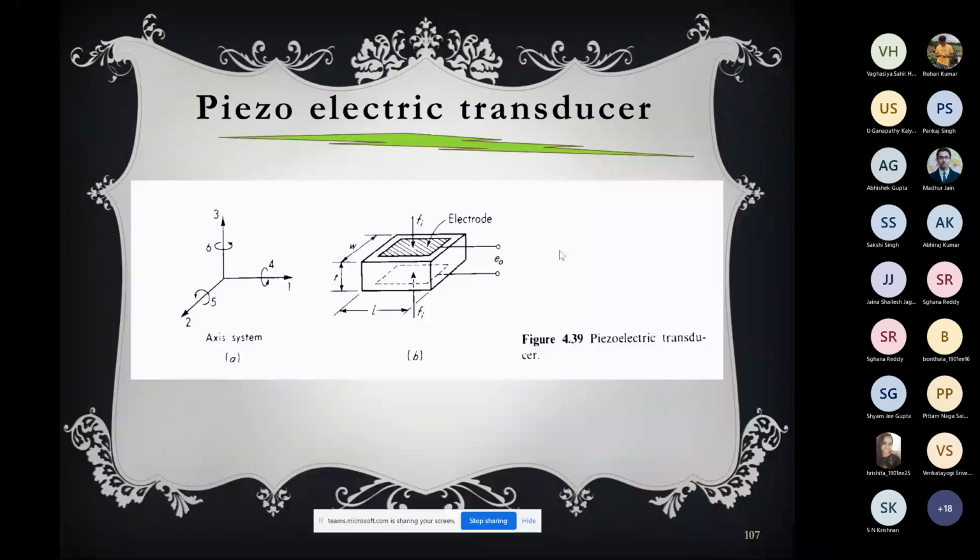So in a refined way, I can say that the magnitude and the direction of the force produce a definite voltage which is proportional, or could be proportional. I'll come to that, whether it is proportional or not. And the polarity also is associated with the direction of the force. If the force direction is reversed, the polarity of the generated charge or voltage will be reversed.